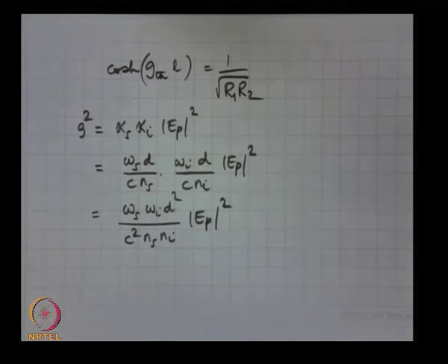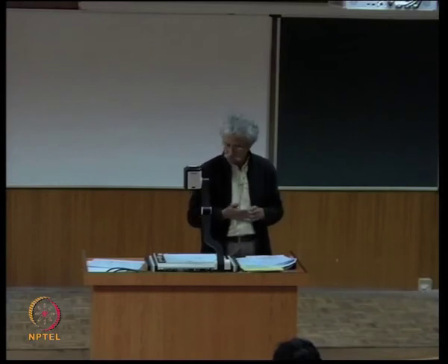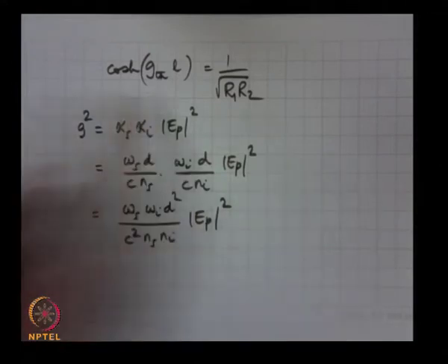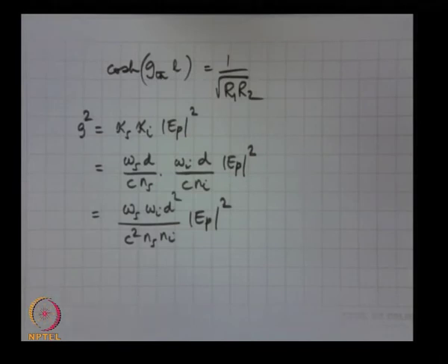Now, R1 and R2 are very close to 1, 98%, 99%, because I need to have a good resonator, which means I need to reflect most of the light inside the cavity so that the intensity of the signal inside is high. So the right hand side is very close to 1. So cos hyperbolic x is close to 1. So what do I do? To get an approximate expression for G threshold, I can expand cos hyperbolic G threshold L, knowing that that value is close to 1.